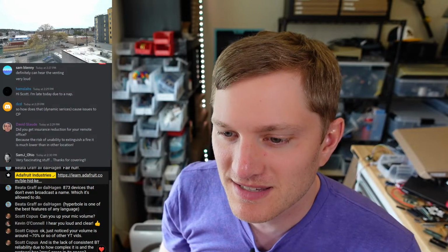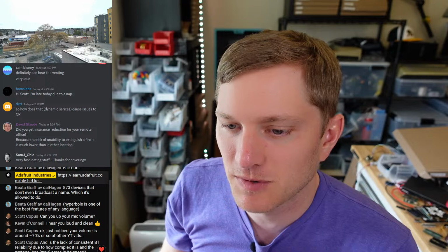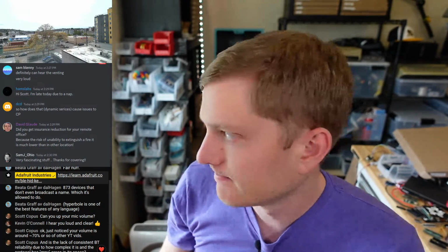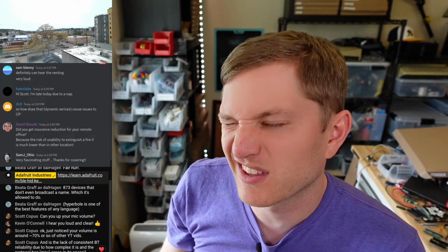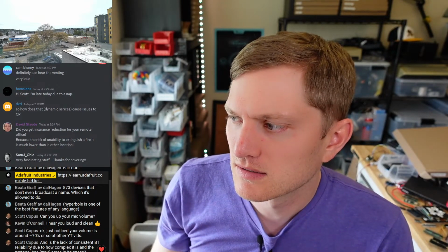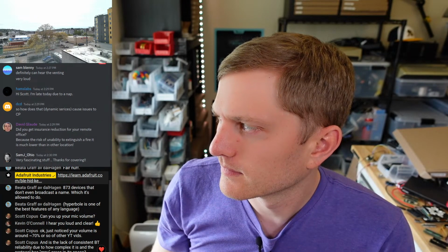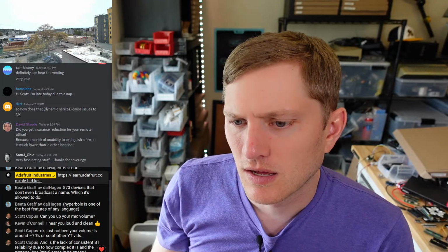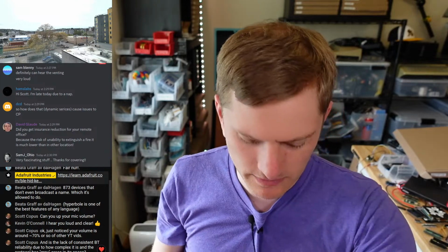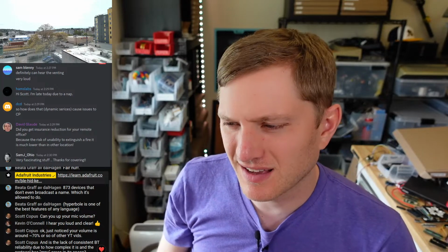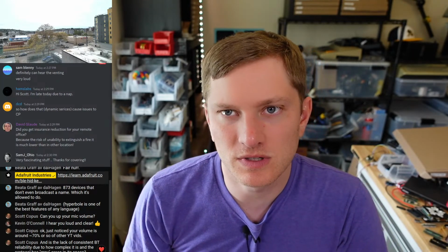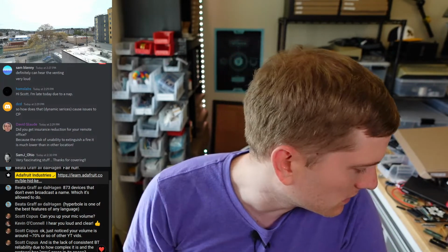Scott on YouTube asks, is the lack of consistent Bluetooth reliability due to how complex it is, and the protocol has gray areas in its specs? Probably. A lot of the stuff that I interface with that has reliability issues is classic Bluetooth, not Bluetooth Low Energy. But yeah, I do have crashes on my watch as well. It's kind of like networking. It's not simple. At any point when you're doing a characteristic read, you could just lose connectivity and you have to deal with that. Just like any networking code, you have to be very defensive in terms of errors and error handling to get it to be reliable.